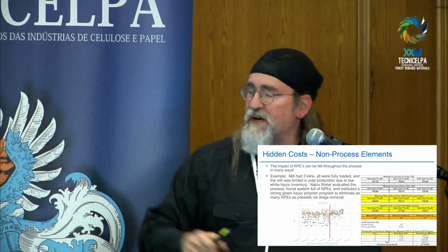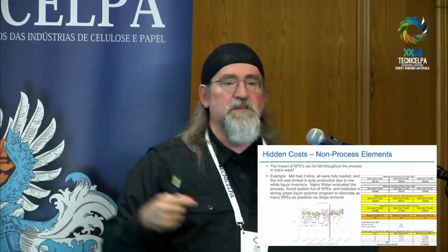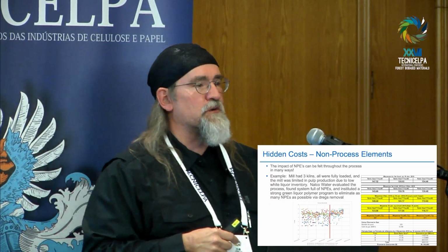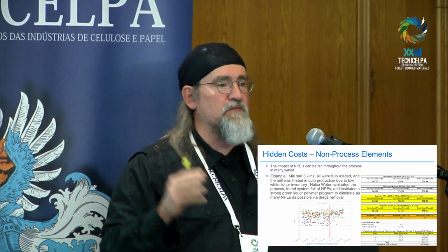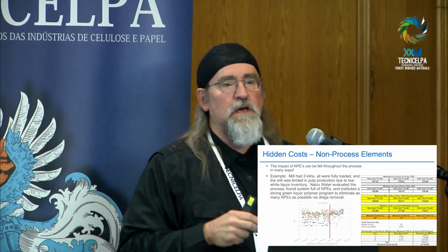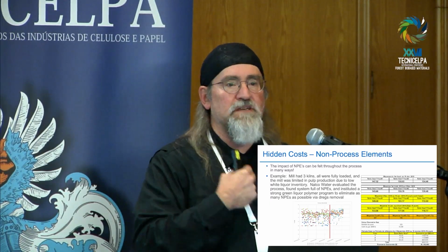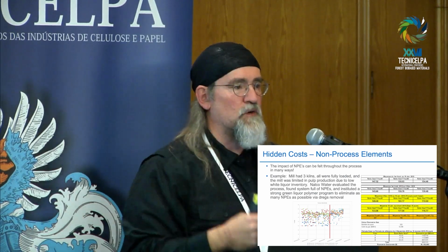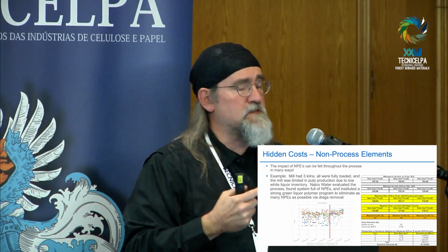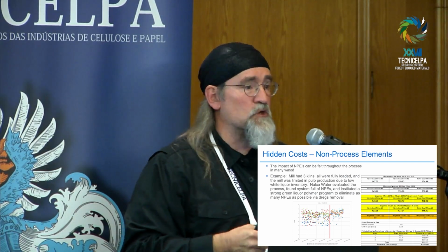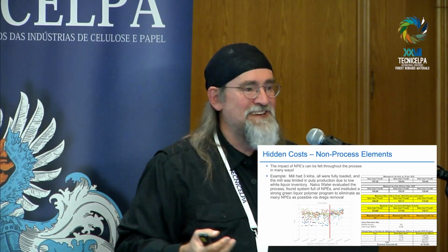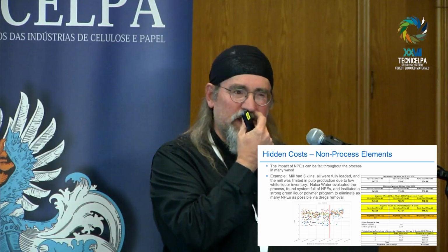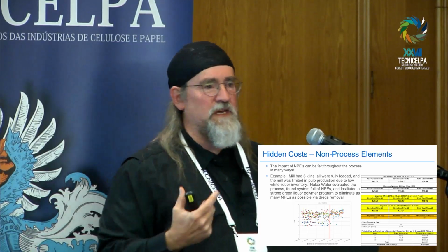This mill had terrible lime mud solids. It's a mill that has three old kilns. All three have to run, try to keep up with the lime. They're always short. It's a bottleneck for the mill for liquor production. So they said, we want something to make the lime mud solids higher going to the kiln. So I started to look, and the lime mud looks like a dregs filter, okay? The mud was almost black. So I saw that, okay, you know what we can do? How about we fix your clarification first?